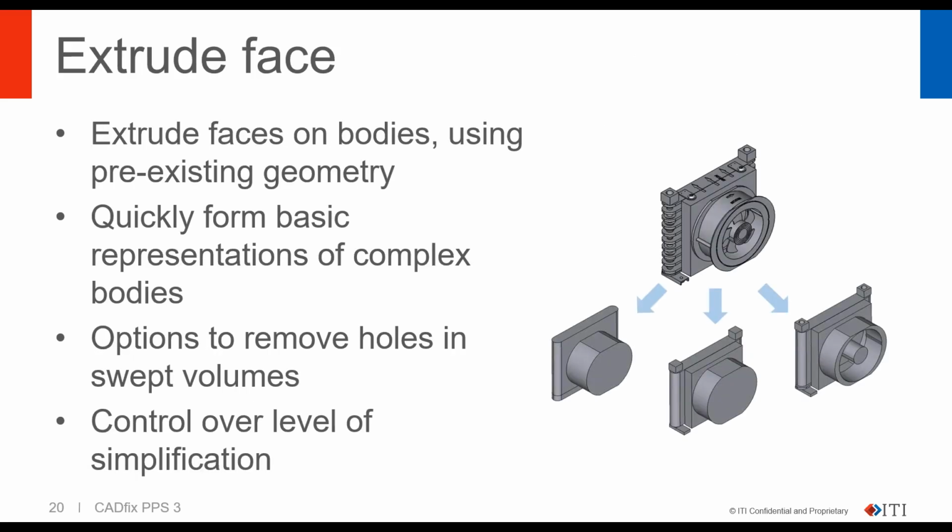The extrude face tool is designed to allow greater control over the simplification of complex components, where successful simplification is subjective. Using the existing geometry of a body and selecting specific faces for extruding allows complex components to be rapidly transformed into more rudimentary representation, whilst retaining key features of the part, maintaining the aesthetic integrity and the volume of the original component.